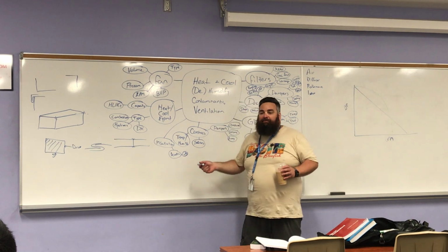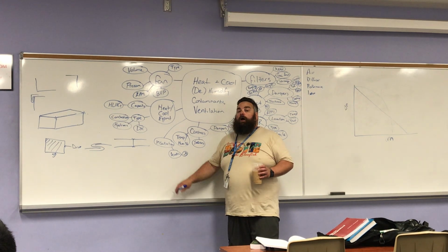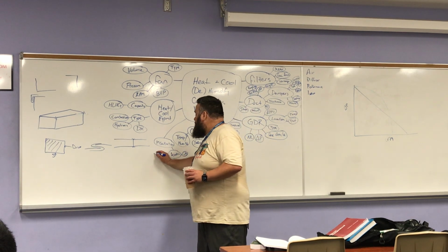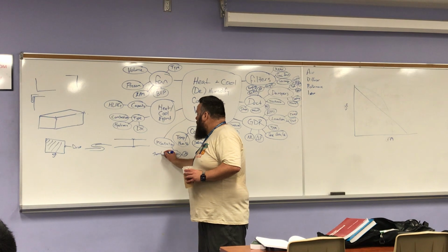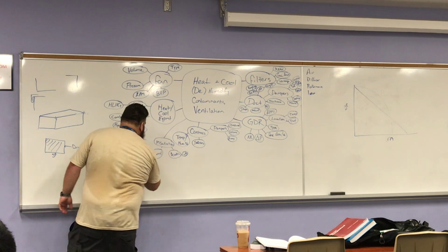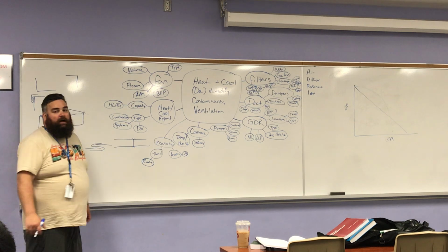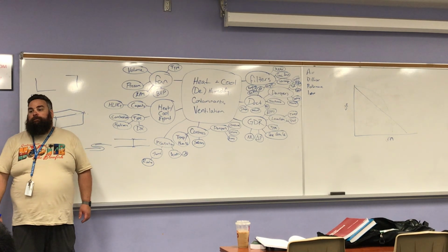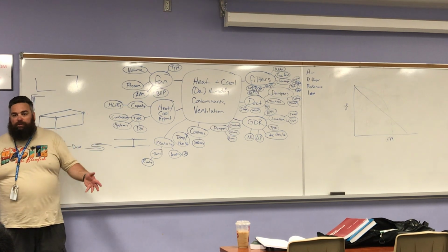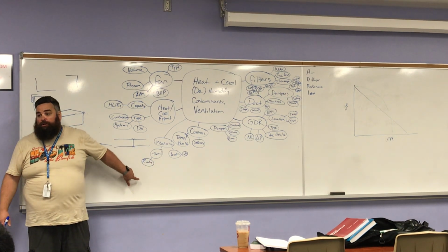Acoustic insulation, this is something I want everybody to remember now, okay? And for the rest of your career. Acoustic insulation is not thermal insulation. I'm going to put thermal here. Properties of thermal insulation. One, we have R value. Does acoustic insulation have an R value? It should. Everything has an R value. Everything resists, everything conducts. It's just how much. Yes, it has an R value. No, it is not sufficient to meet our thermal insulation requirements.